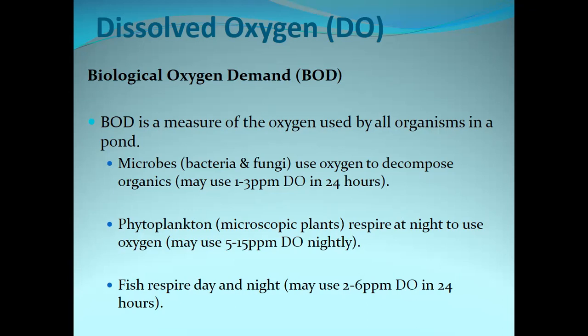At nighttime, they cease producing dissolved oxygen while they continue consuming dissolved oxygen. So you realize now your dissolved oxygen level could go critically low at nighttime, because you have your fish using oxygen, your plants still using oxygen but no longer producing oxygen via photosynthesis, and your bacteria still using oxygen too. So the biological oxygen demand at nighttime will be felt greater. Your level could drop so low that it could cause problems for your fish and end up with fish dying overnight from a lack of dissolved oxygen. During the daytime it's fine, but at nighttime it could become extremely problematic.